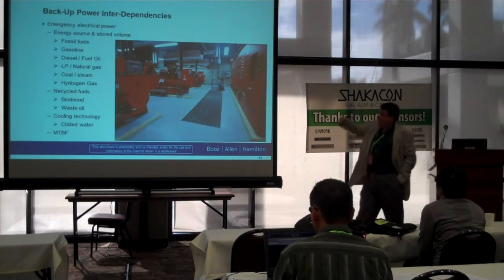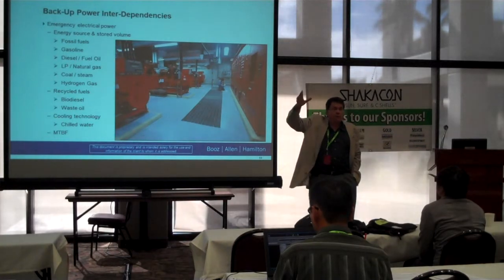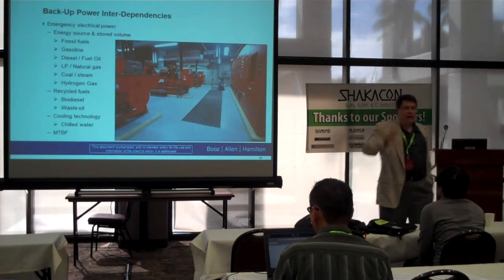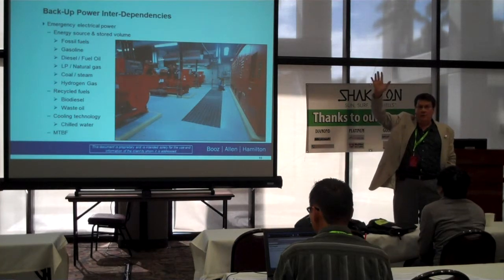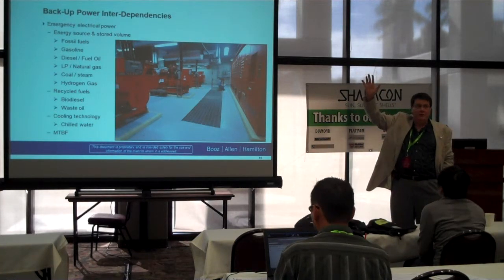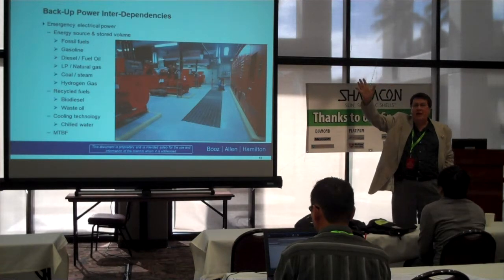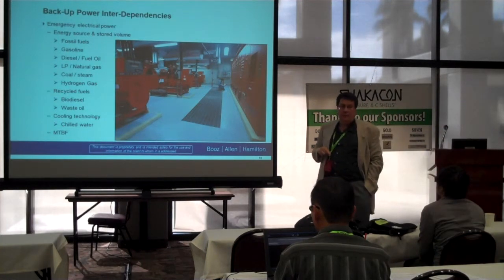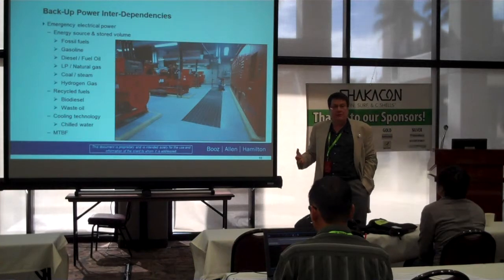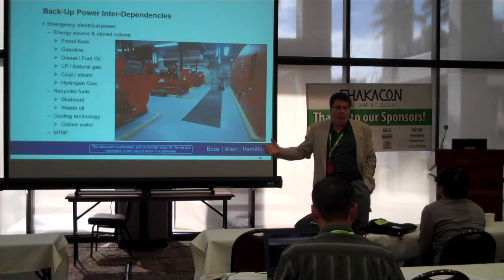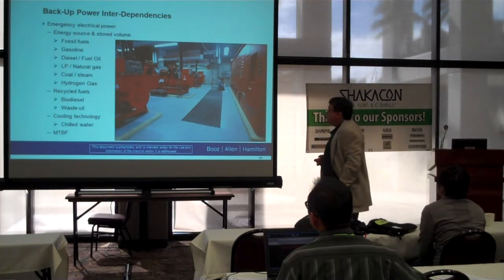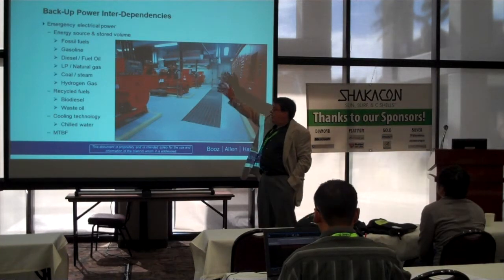Backup power interdependencies. People don't have refueling plans. It's like, oh yeah, we got 3 days worth of fuel. Does everybody know how long it was before they were able to move fuel into New Orleans? It's over 45 days before a tanker truck got into New Orleans. If you're running a backup generator, you've been out of power for 40 days. They didn't have that much of a problem because most of their generators were below grade, and when the water came in, their generators were covered with water, so they didn't run anyway. But those are the kinds of things you have to think about.